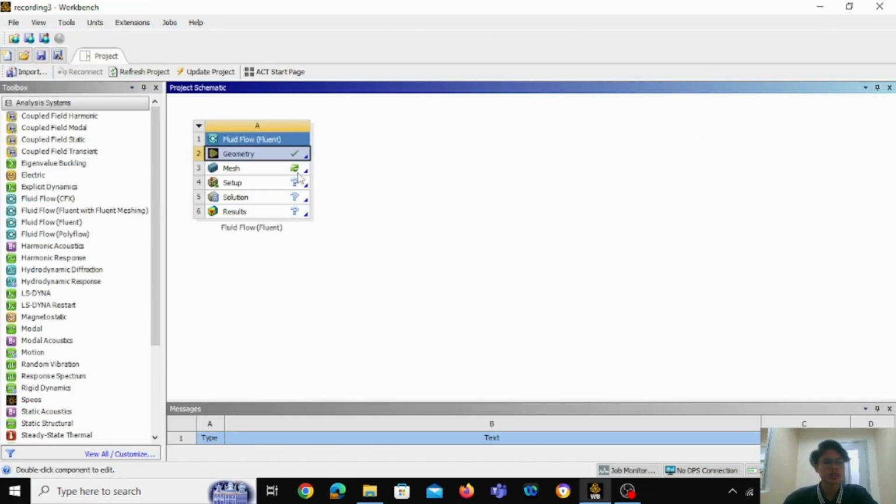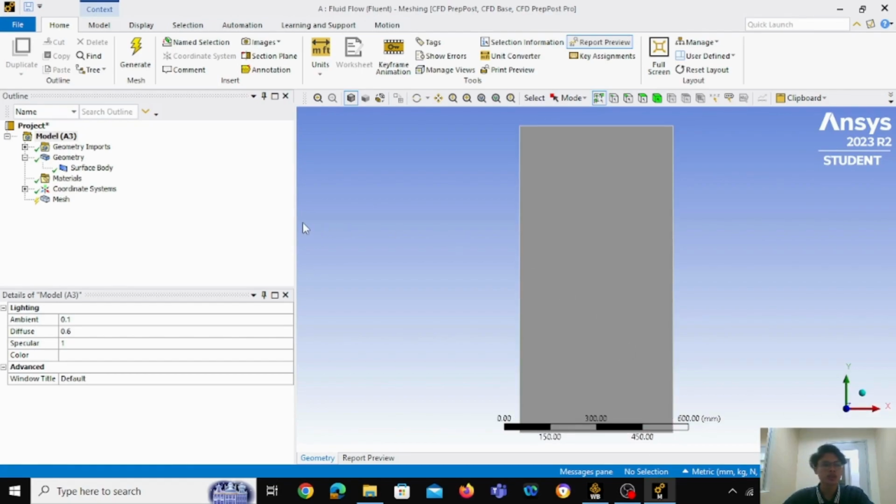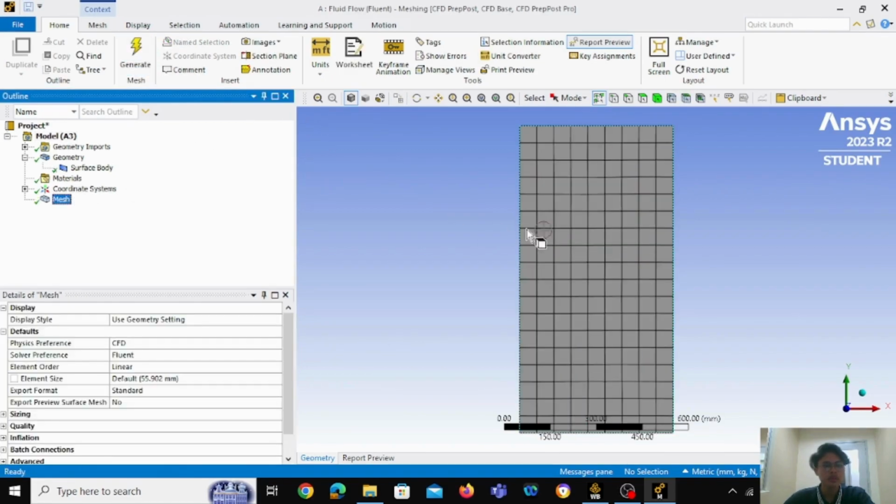When I click mesh generator, it will execute another package for me to create the 2D mesh. So I go to 2D view. Okay, if I simply click on generate mesh, it's going to generate roughly the worst mesh possible because there is no control by default. We cannot use this because it does not have the characteristics that we want.